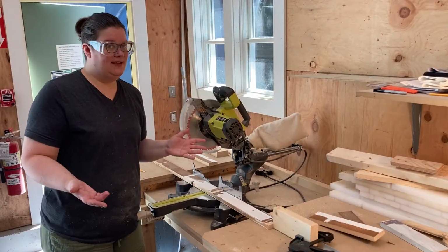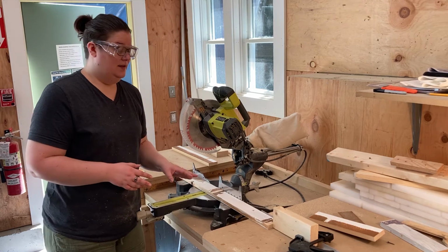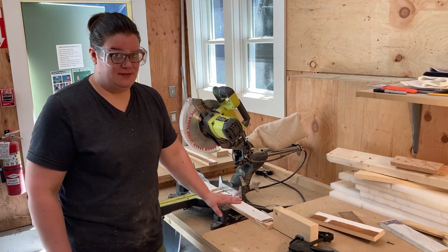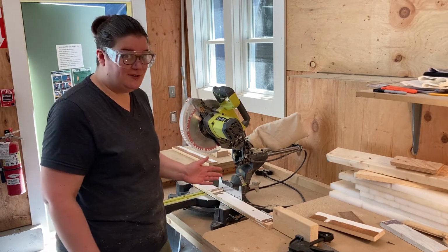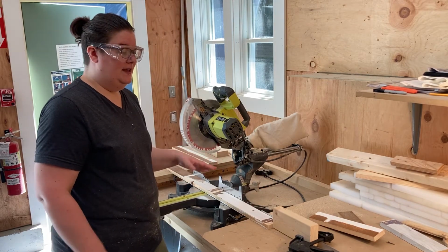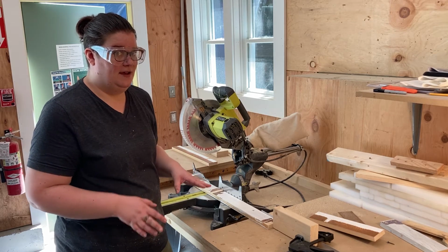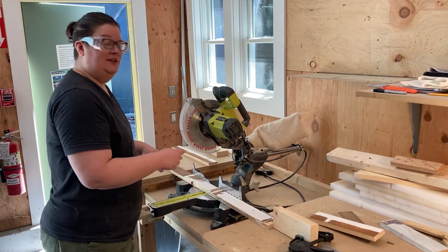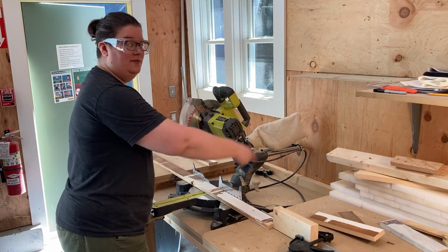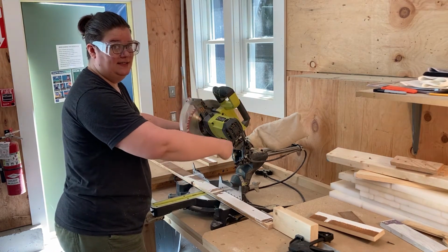So one safety tip when using a stop like this with a saw, you're essentially capturing a piece of wood between two hard surfaces. You're catching it between the block and the blade. And if it wants to move, it doesn't have much of anywhere to go except for to kick upward. Thankfully, these saws cut away from you, so the blade is rotating toward me at the top and away from me at the bottom where it's contacting the wood.